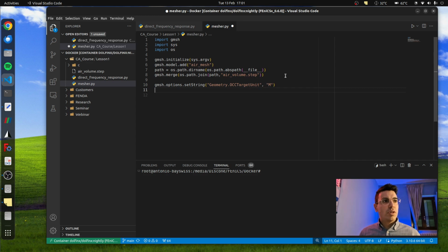Then we are going to assign some basic mesh size value. There are a lot of them, but we will stay pretty good with the standard mesh size max parameter. So since it's basically a parallelepipedic geometry and we don't need to, you know, refine in some areas or little sub volumes, we are fine with that for now.